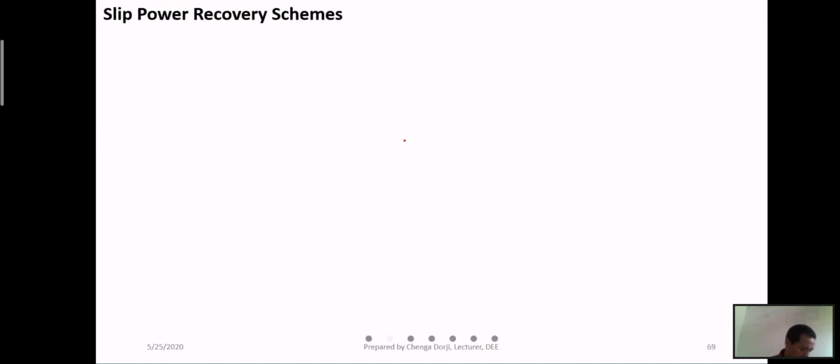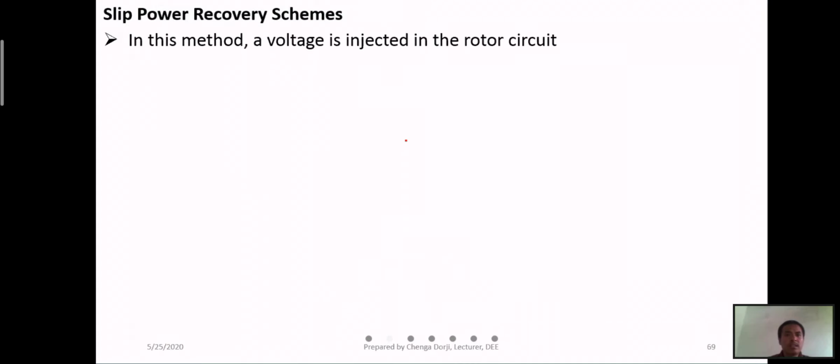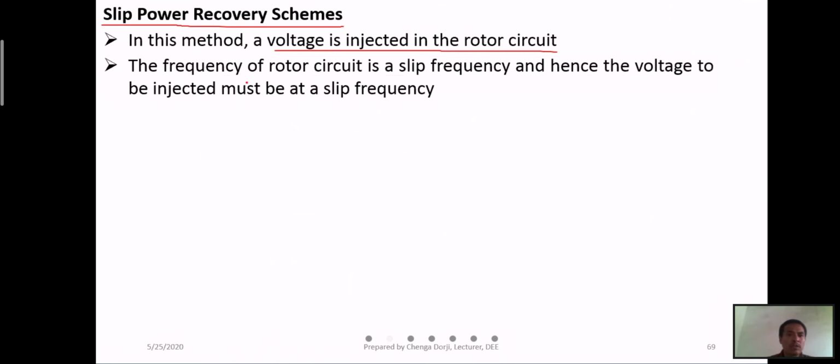Then slip power recovery schemes. In this method, voltage is injected into the rotor circuit. The frequency of the rotor circuit is the slip frequency, and hence the voltage to be injected must be at slip frequency. That you have to keep in mind.